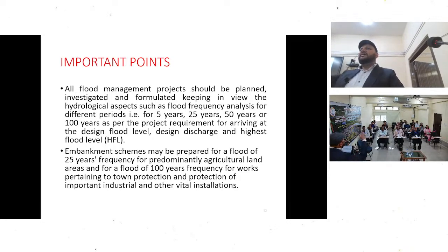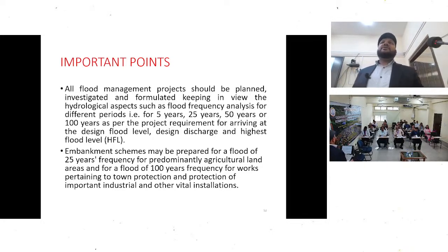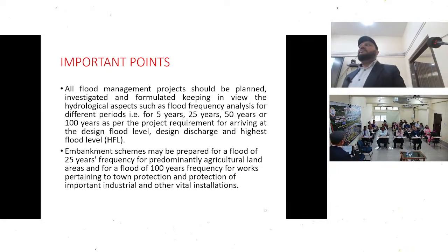If we take a 100-year flood frequency, then the HFL will be very high. Suppose we are constructing an embankment. Its height comes to 2.8 meters from the bank line for 50 years. But if we take 100 years, then it may come to around 3.5 meters. Then the cost will increase many fold.